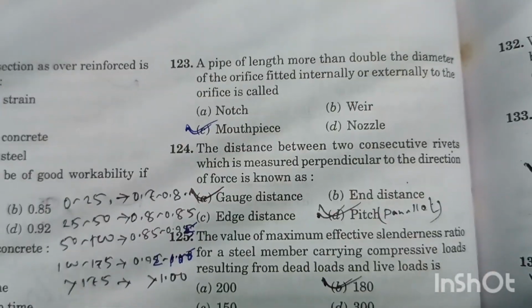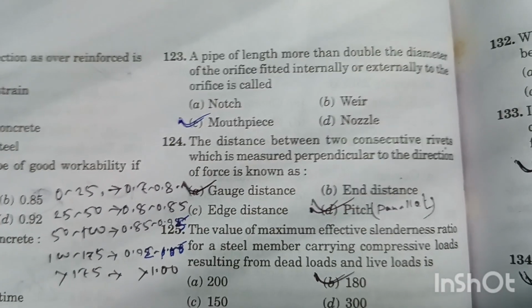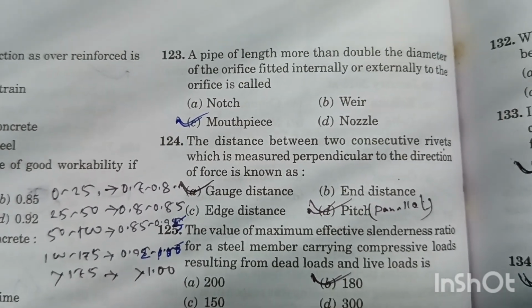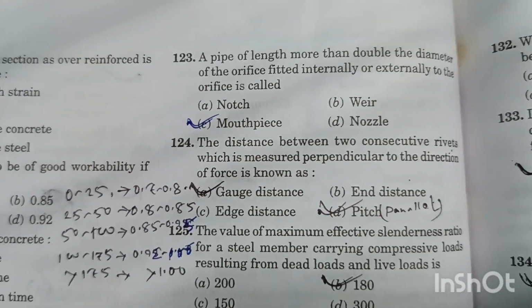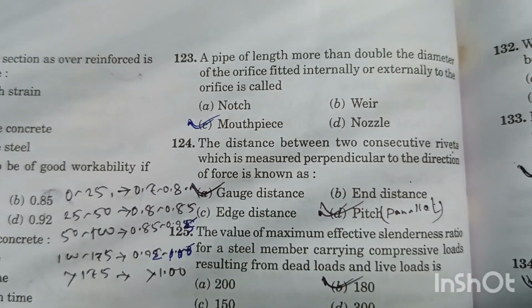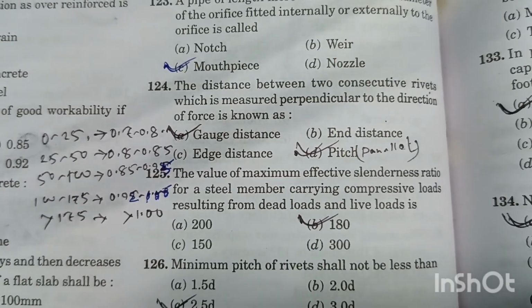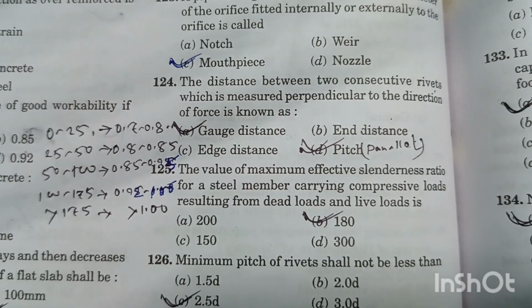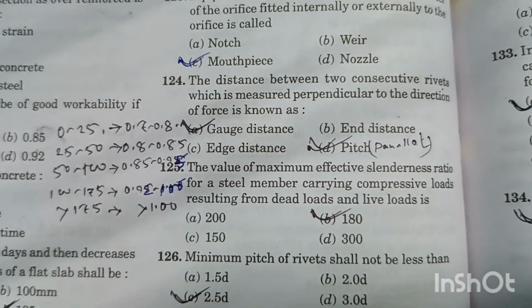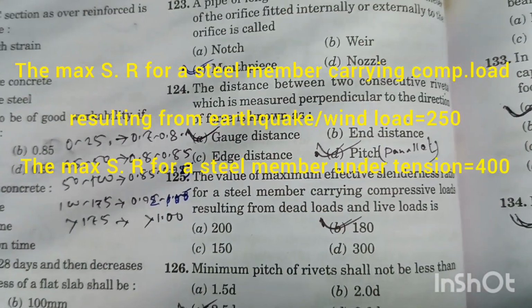Question number 124. The distance between two consecutive rivets which is measured perpendicular to the direction of force is known as gauge distance. Option A is the right answer. If it is parallel to the direction of force, it will be known as pitch. Question number 125. The value of maximum effective slenderness ratio for a steel member carrying compressive loads resulting from dead loads and live loads is 180. Option B is the right answer.